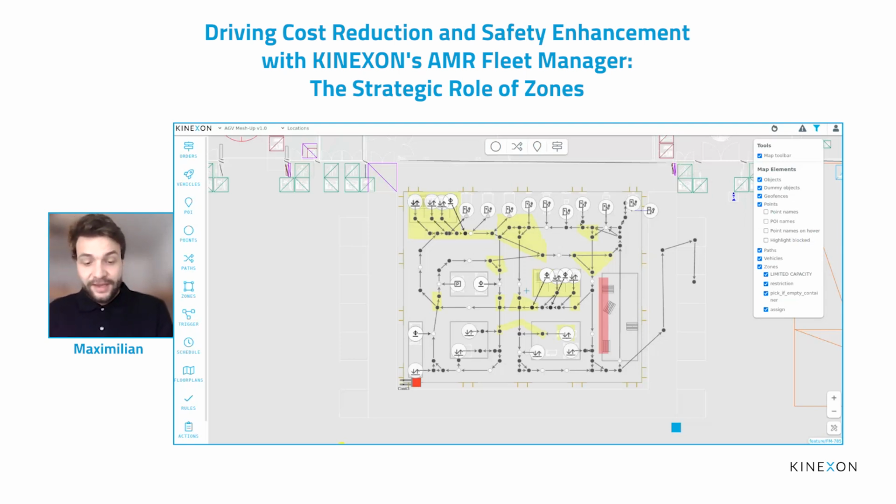The other way around, if the old vehicle approaches the shared area first, it would request the area, and if it is free, it would set a virtual traffic light in front of the area to the vehicles that are VDA 5050 compliant and stop them right in front of that area.